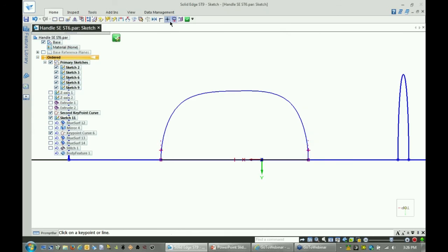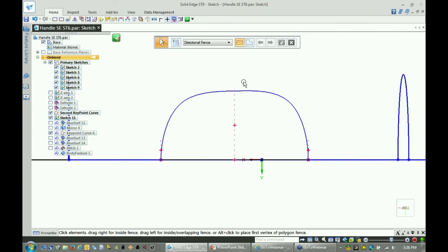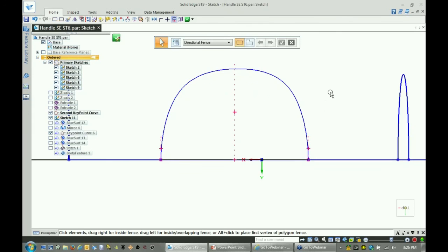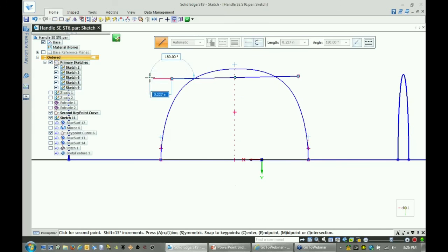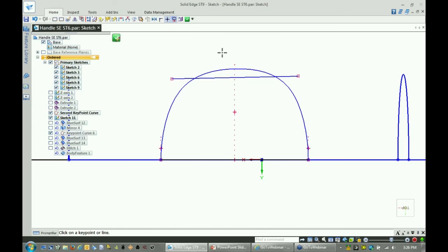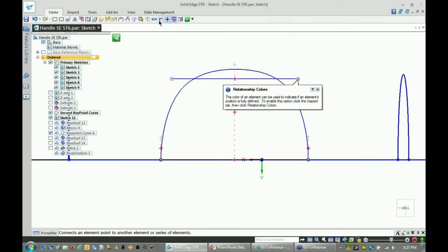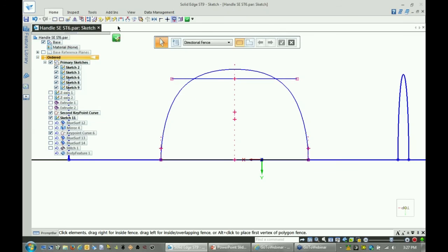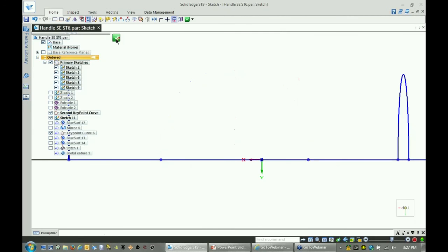And what this allows to do, it allows to align actually midpoint with this polygon controlling point. So we want to make sure we stay symmetrical. And I can even connect couple points with a line and make sure that it's horizontal, and also to make sure that it also stays symmetrical. So you have full control. And if you want to turn it into reference geometry or construction geometry, you're welcome to do that. Just pick these two lines and you're pretty much done.